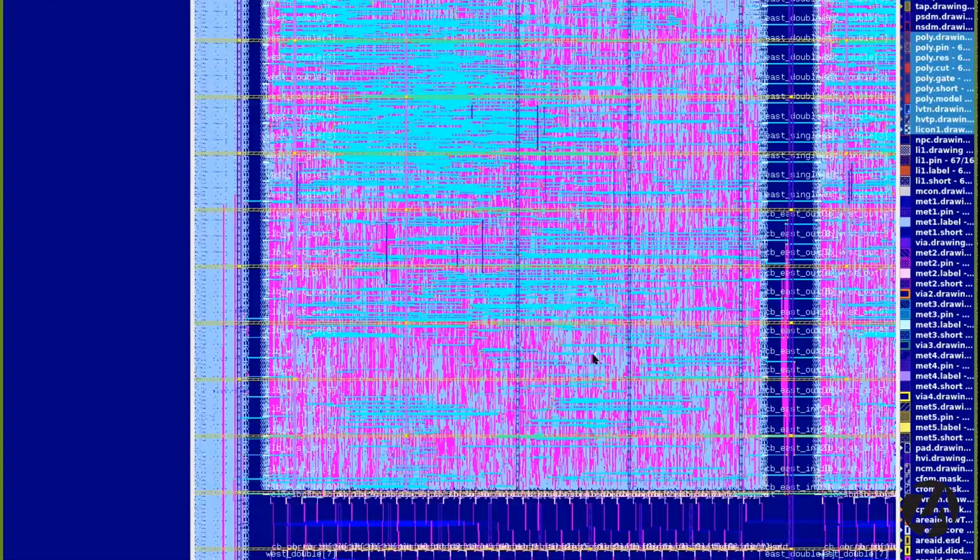So for example, OpenFPGA has the same idea, but they've gone and added custom cells. They've added a custom mux or a latch. I think they called it a flip-flop, but it was a latch for storage within the LUTs.